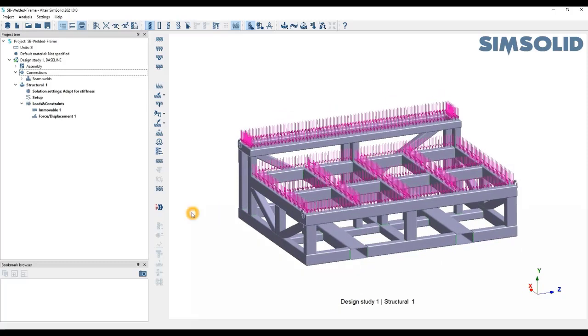Just so you know, you do have other loading options as well. We won't be touching upon them, but you can use enforced displacement. If you're trying to replicate real test data and you don't have the forces behind it, you can use an enforced displacement to emulate that distance traveled. We can apply inertia loads, gravity loads, so any G loads that you want, any inertia relief. You can do remote loads, bearing loads, hydrostatic pressures, etc.